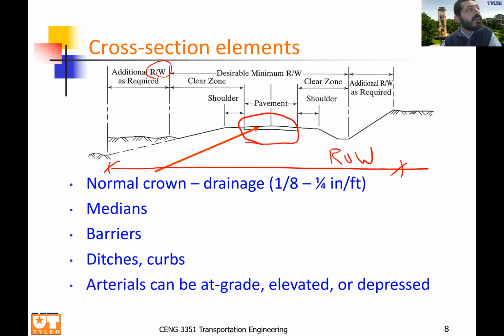For example, if I'm driving from Tyler to Dallas on I-20 and there are 2 lanes per direction, who said we may not have 3 lanes per direction soon, maybe in 5 years or 10 years, depending on the need. But the right of way will give us that capability.